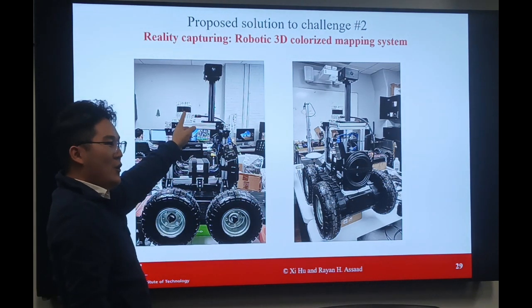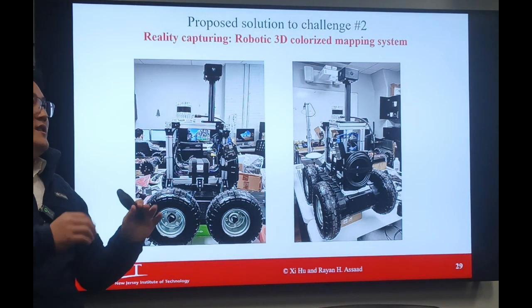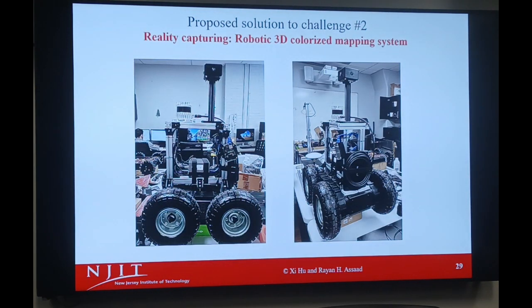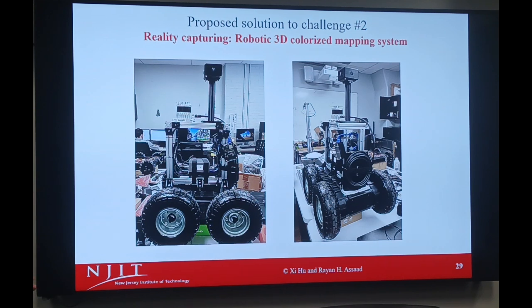And this is a LiDAR. This is the Ouster LiDAR 128 beam. It gets a 3D representation of the environment through a set of dots or points. It's kind of hard to imagine. You can understand that when we represent a 3D space, we can use edges and surfaces, right? But if we do a sampling from that, maybe we just need a part of the information. It's going to be some dots. Roughly, we can still represent the same thing. That's called a point cloud. It's a cloud of points.